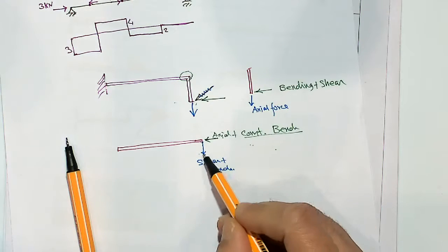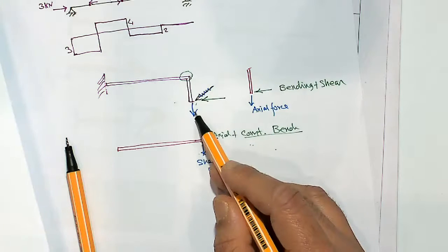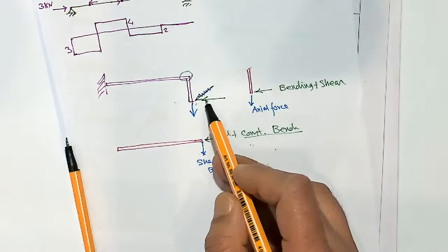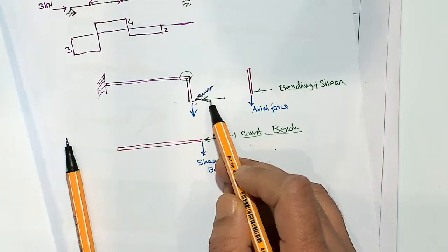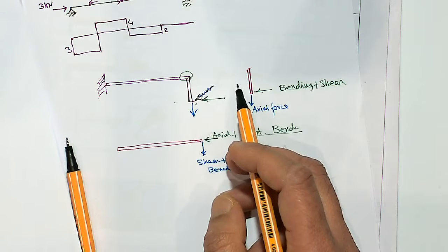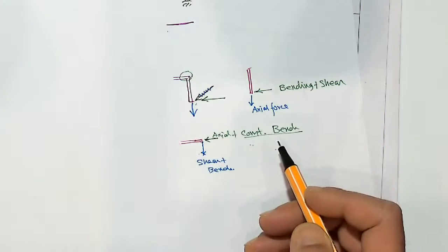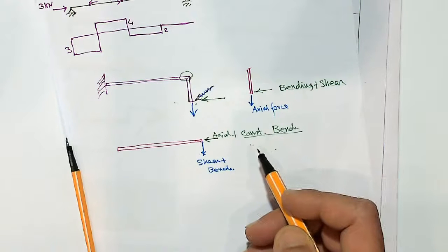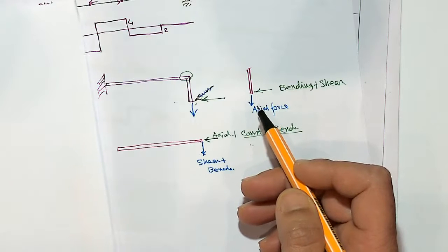So it will have bending due to this, bending will increase due to this blue load, plus there would be a constant amount of bending due to the horizontal green load. So not zero. Why would that be zero? No, it won't be zero anywhere. But this blue load will increase the bending as you go along, so it won't be constant. For the green component, it will be constant bending moment.